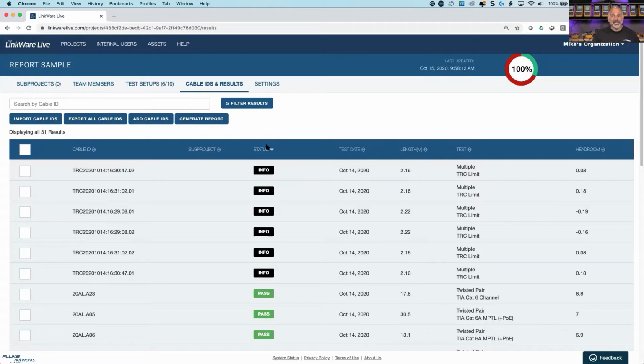If you're having testing done, in addition to the PDF report that you may receive or the printed report that you may receive from the people doing the installation, we strongly recommend that you request the FLW file as well. And this is the Fluke LinkWare file. This file gives much more detail into each one of the tests than we see with the PDF or printed report. I will show you how to go in and download that FLW file, and we'll look at how we import that into LinkWare PC.